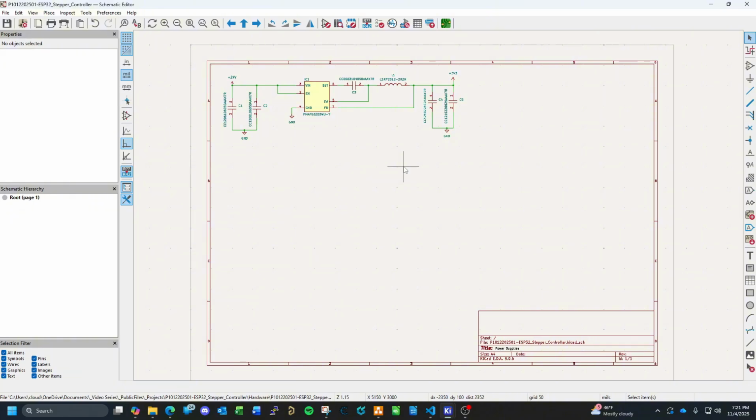If we can find a small enough 3.3 volt power fan similar to the ones used on the Raspberry Pi, maybe we'll go that route, not even worry about designing another power supply. But I have a feeling we're going to have to do a 5 volt supply just to operate the fan, which is perfectly fine for the cost of the parts and to get a more professional grade product at the end. It doesn't bother me in the long run if we have to add a 5 volt supply.